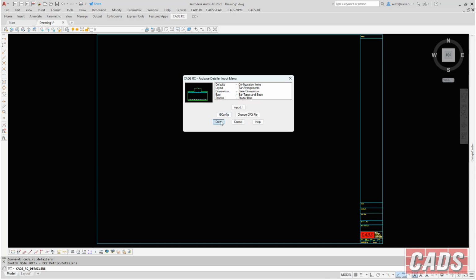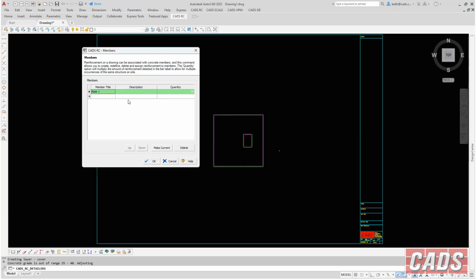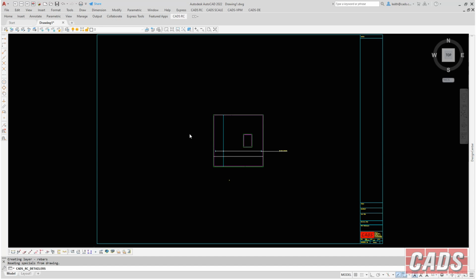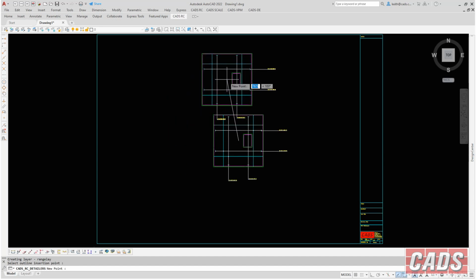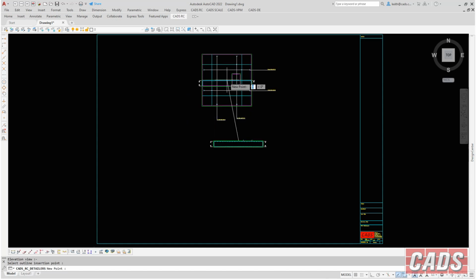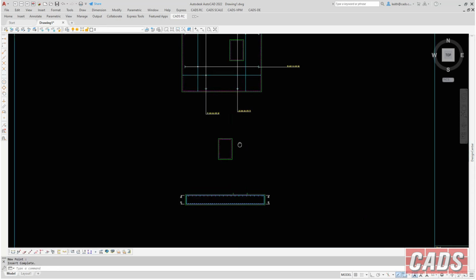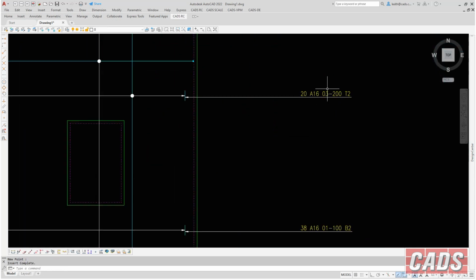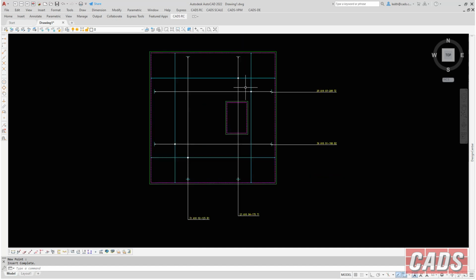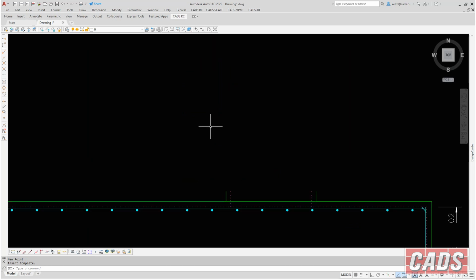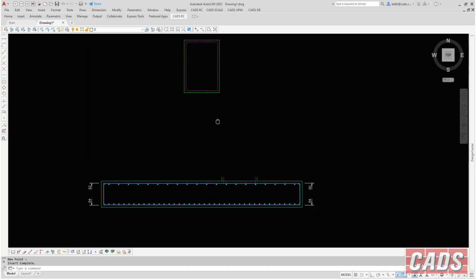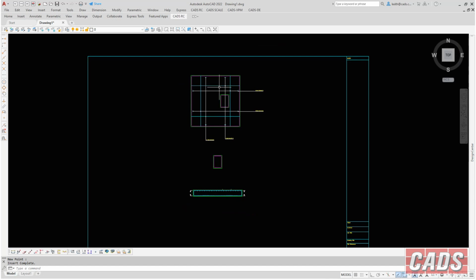bring it in and say draw. So you can see, we go okay there, you can see it's brought one of the bases in, the one with the skewed column look. There we go. That's the base with some U-bars in it. And then finally the column. There we go. So let's have a quick look at that. You can see we've got the 16s I wanted in there earlier. All the bars are detailed and there's a base detail there. Okay, so there's the actual detail.